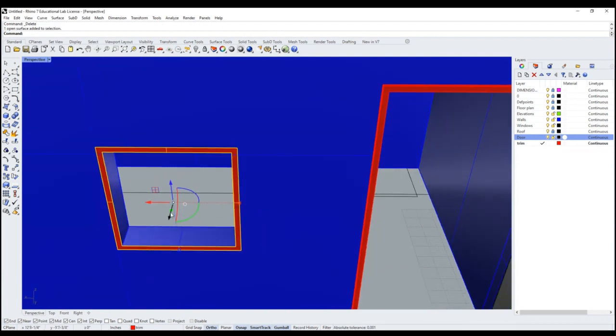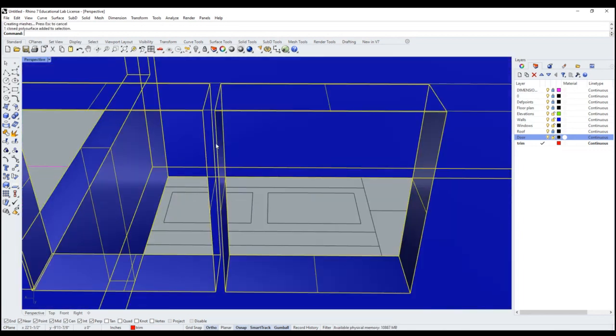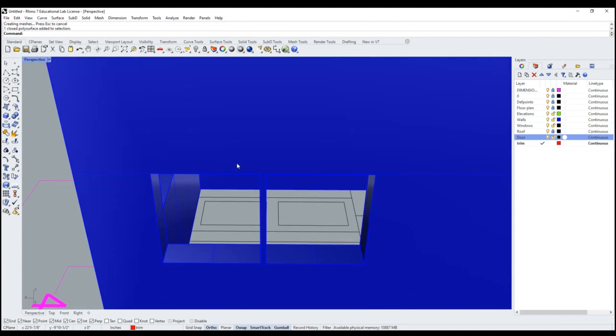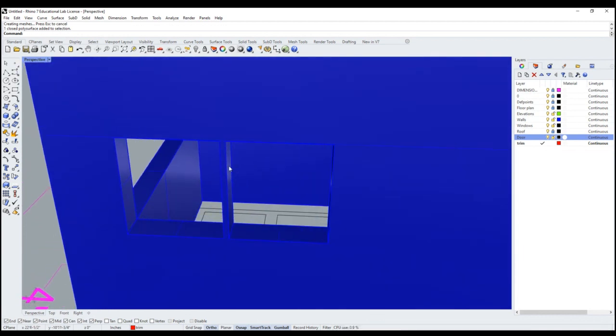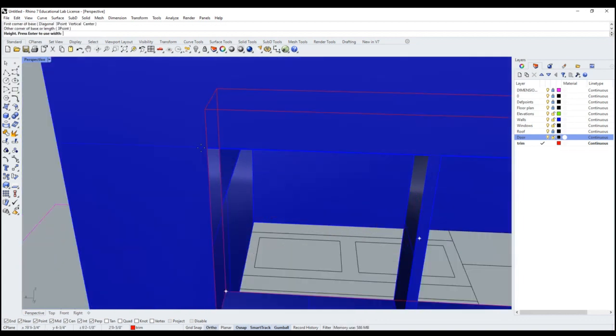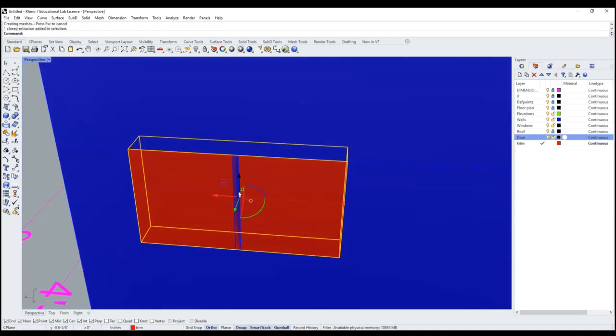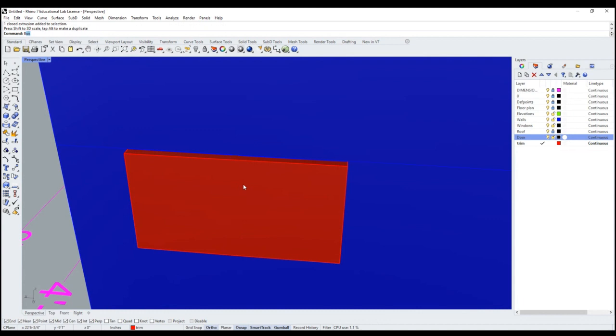I'm gonna grab the surface and extrude it 1 inch. And this one here we're gonna actually fix up because it shouldn't be this way. So we're gonna create a box in here, and we're going to stretch this box slightly out more.